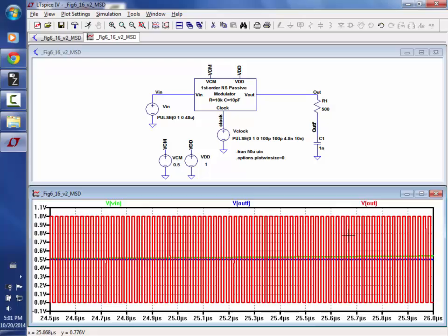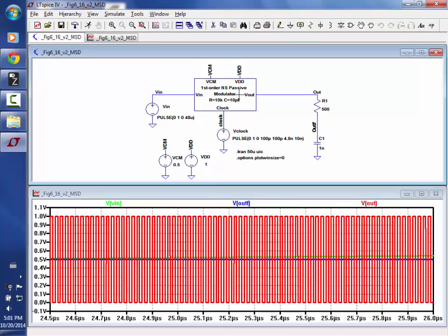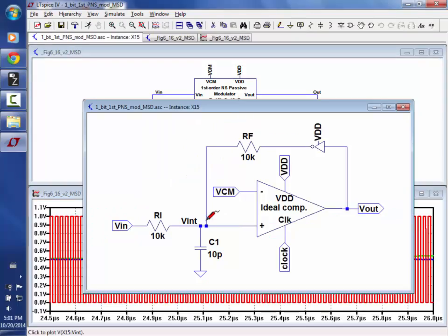This isn't as big of a problem, and maybe I'll show you the analog modulator here in a moment for the analog topology. But what happens is, because this node is wiggling around and it has a certain shape, when you put in a voltage near the common mode voltage and this voltage changes, the average amount of charge that you push in here can be equal to the output amount fed back when it goes 1 0 1 0 1 0.